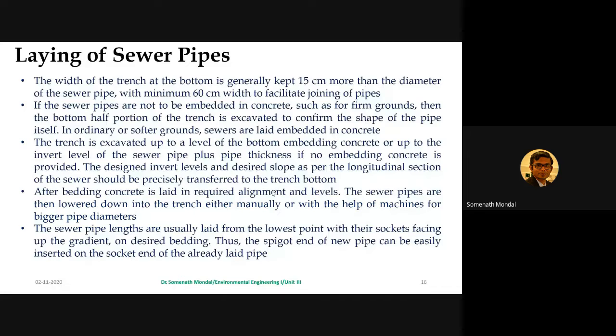Now, if you encounter such kind of ground, what you need to keep in mind is that in case of concrete, we simply lay the pipe when the concrete has not set. During that time, the impression created can ensure uniform support for that pipe.